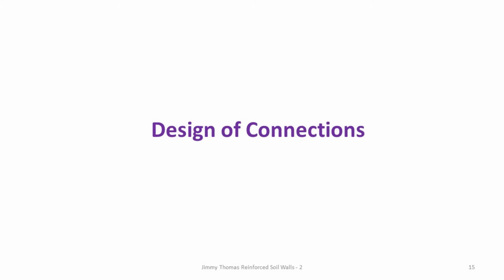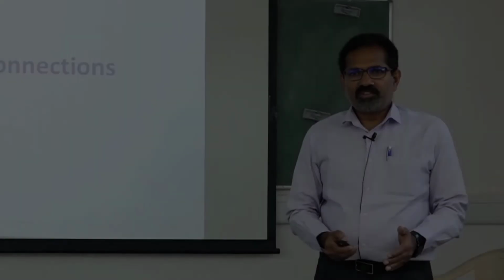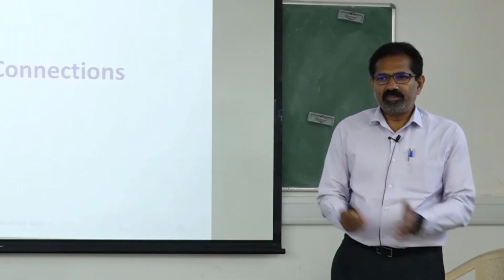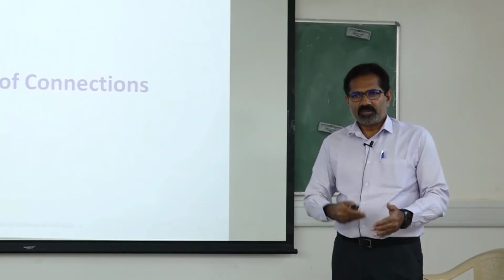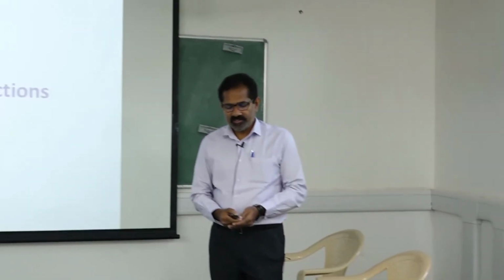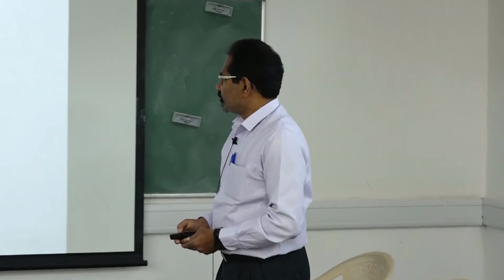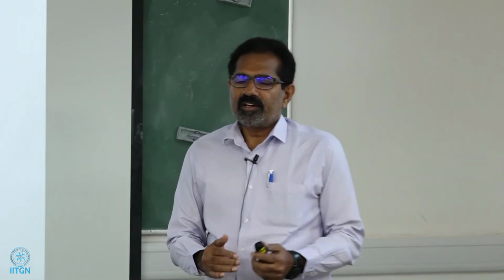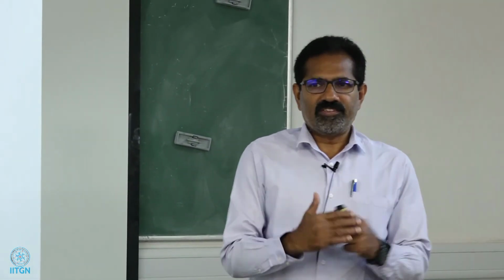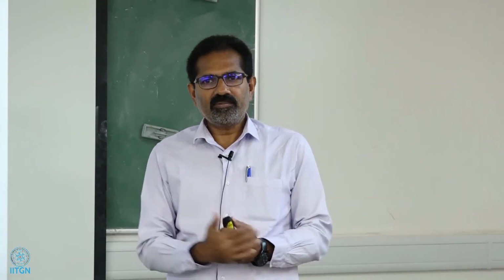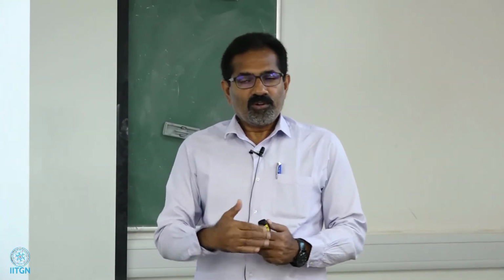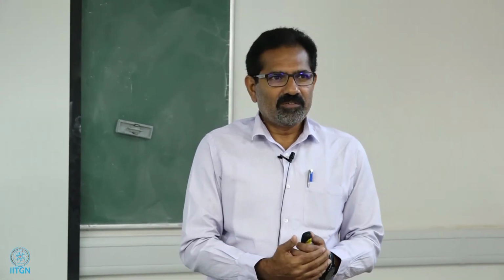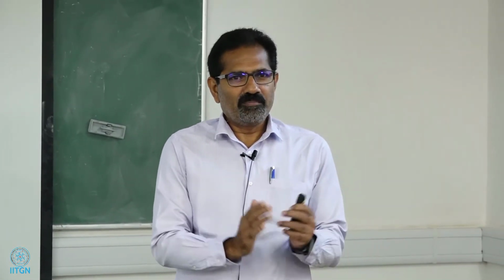Okay, that was about the limit state design. It was just to explain the load combinations A, B, C, and the logic behind the different partial load factors and partial material factors. Then again, as I mentioned earlier, the connection between the reinforcement and the facing is an important aspect. Especially in India, we have a lot of failures. If you look at the failures, many were due to poor connections.